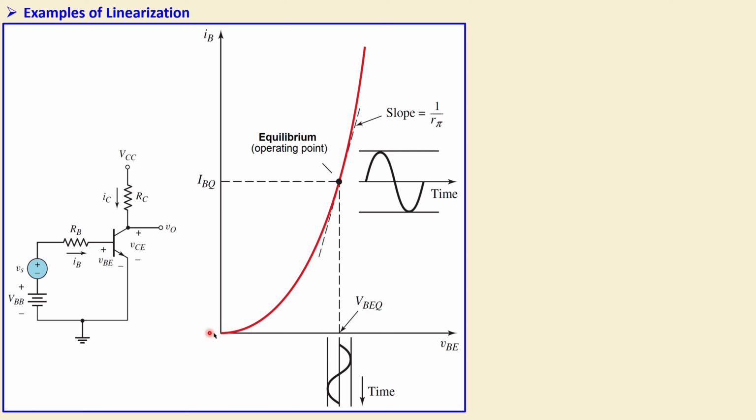Now you can see here how that is related. So the base current, this one, is related to that base emitter voltage in this form. It is not linear, it's also not quadratic, it's actually exponential. You can see that from this expression, which is actually a simplified form.